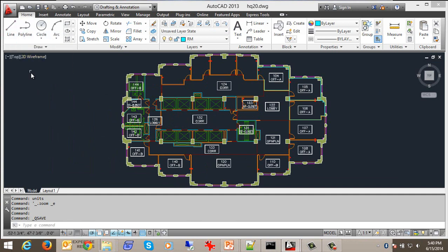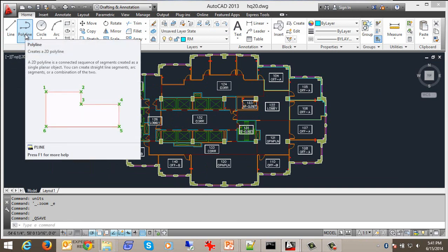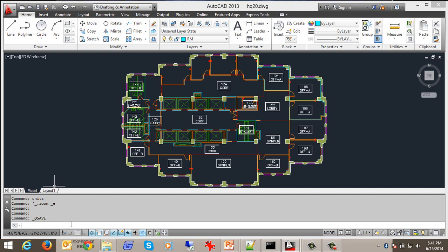You can get to that polyline command by going to the ribbon. There is a ribbon-based item inside of there. You can also go down to the command line and type polyline or P-line to start that command. You can also use the ribbon up top here as well. But for those that haven't been dealing with it, you want to be able to draw it out.